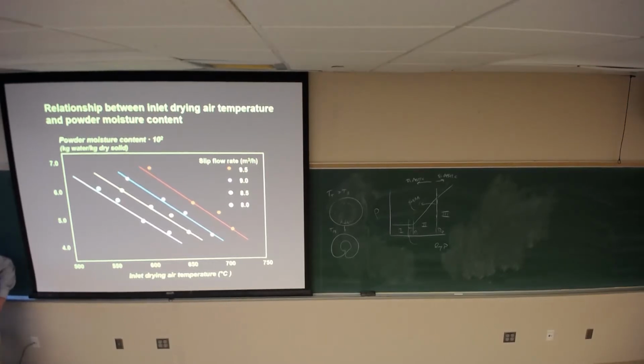metric tons per hour. They're going to set up this spray dryer, and they're going to run it until it reaches steady state. Then they collect the sample. And then they're going to change the parameter, run it until it reaches steady state, and then collect the sample. And so they're actually doing this test on a spray dryer in a factory. You're creating hundreds of tons of material, and then the question is, can you use it? Maybe. But by doing this, they then mapped the sensitivity.